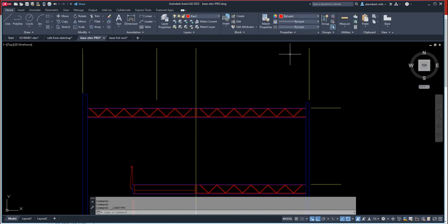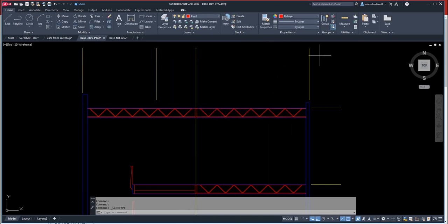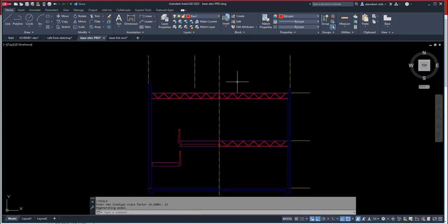And you can't use a line type from an XREF. And what I've been doing is selecting line types of this from the XREF. So simply select that and change that to center. And let's see what kind of LT scale I'm going to need to adjust to. 0.1? No? There you go. So my LT scale is 12 right now. I can see it in model space, but when you get to your paper space, you might not see it.